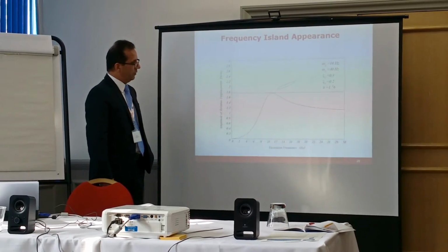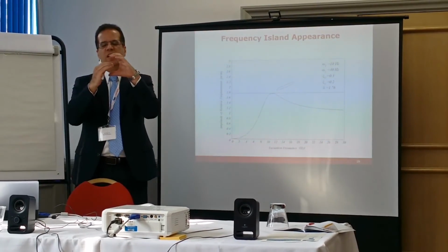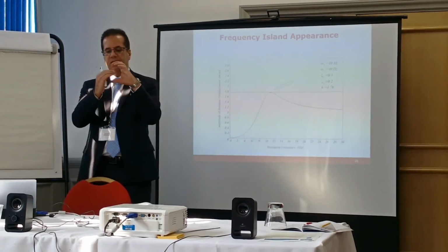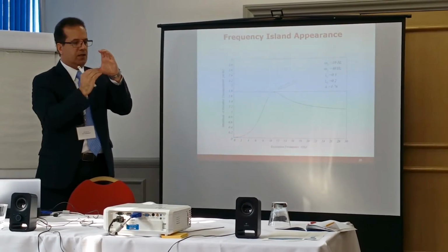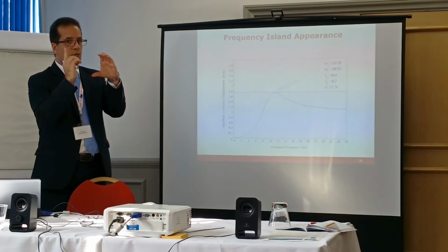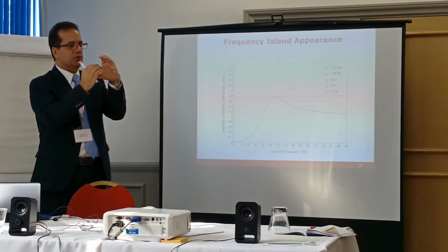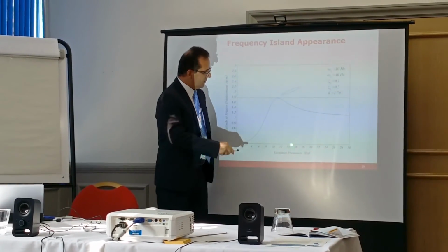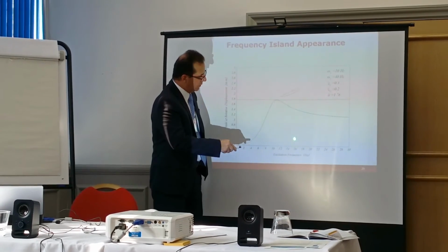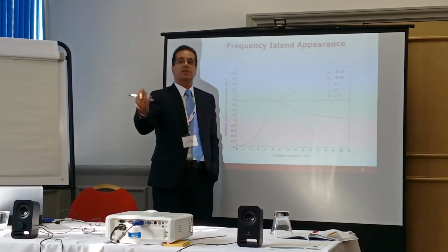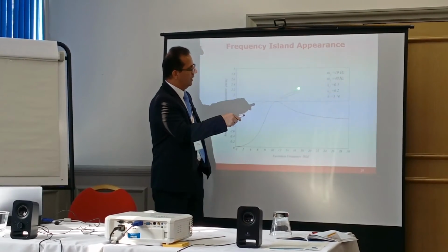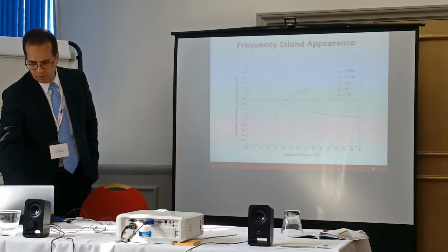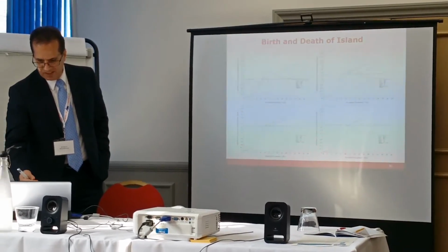Very interesting phenomena when we have the gap size close to the peak value of a linear system. So the primary system is barely or not touching the secondary. But because of some excitation, for one fraction of time, it touches the secondary, but it's not going to let it go. This is what happens. So the system is supposed to vibrate between these two points. This is the amplitude. At this frequency, because of some sudden excitation, it jumps to an island and it keeps vibrating there. Very interesting phenomena, which we published several papers based on.